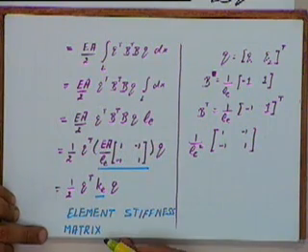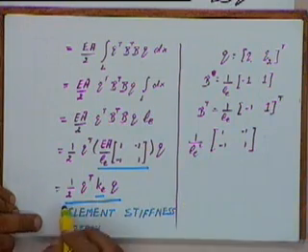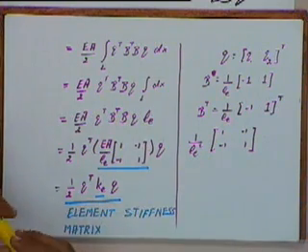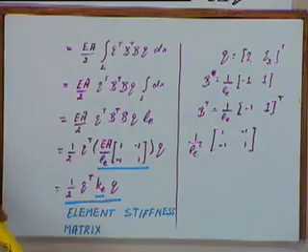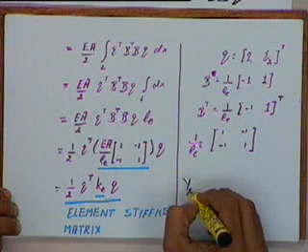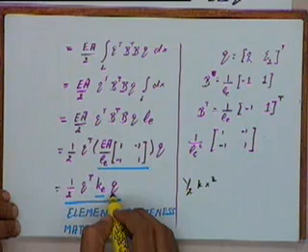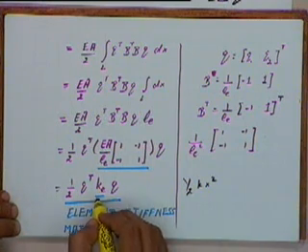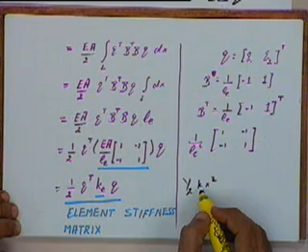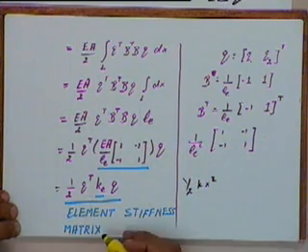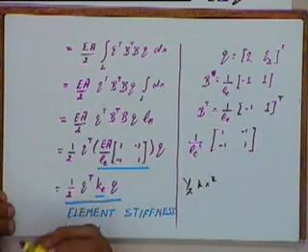And why do we call it the stiffness matrix? That you can see from this expression for potential energy. You can compare this with the potential energy of a spring, which is half k x squared. This x is the same as the deformation over here, and this k is a stiffness. So this KE is called the element stiffness matrix. It basically relates the deformations with the strain energy in the object.